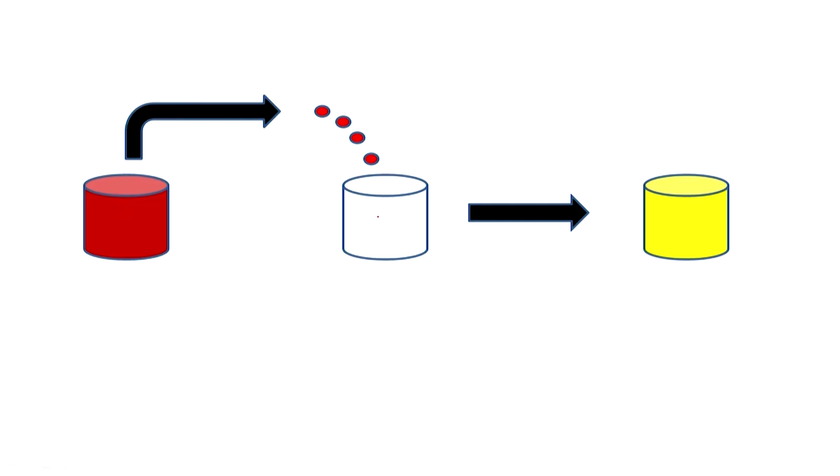So, what will happen is this chloroform in the water will form a chloroform dispersion, and this dispersion contains the polymer chain. Now, if I heat this dispersion beyond the boiling temperature of the chloroform, the trapped chloroform will leave the solution.